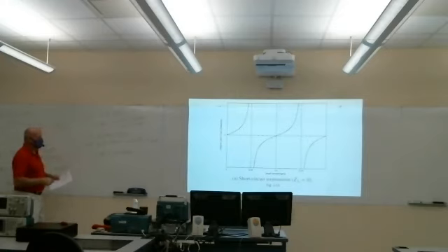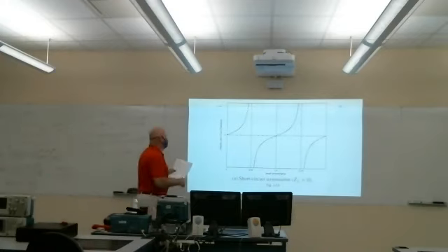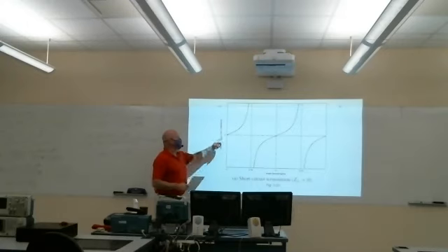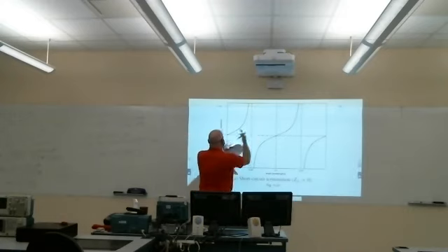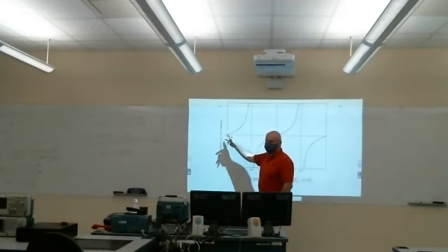And that's actually this plot here, a plot of the input impedance as a function of L, where this is the positive length, from the load back to the source. So this is kind of time reversed, but reversed in space. So if I flipped it this way, this would be my load, and I'm going back this way. Again, at the load, you notice the input impedance is 0. It's a short circuit at the load.